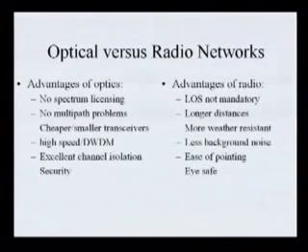Your 802.11 here is 2.4 gigahertz, so you're talking about 30 times higher in frequency. Now, that frequency band is totally unlicensed, 57 to 64 gigahertz, you get 7 gigahertz of bandwidth. But the problem with that particular band is that you can't go very long distance. You can go about a kilometer, and that's about it. But for our campus, a kilometer is really almost reaching from the north to the south part of the campus. All right, so we're using that.